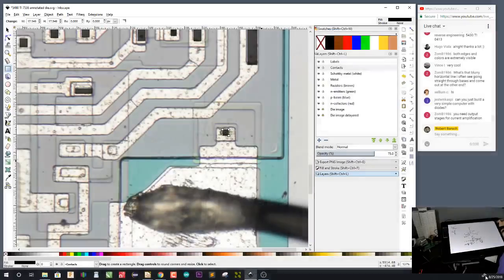All right, so anyway. Can you build a very simple computer with diodes? Yes, and the answer is you do need intermediate stages, because every time you have a diode, you lose some voltage. So eventually you lose all your voltage. So you would either have to keep stepping up your supply voltage or put in some amplification. And that's really all there is to TTL, to be honest.